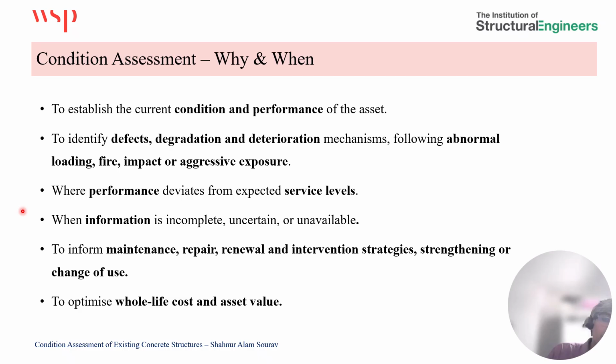So why and when do we do condition assessment? We do condition assessment to establish the current condition and performance of the asset. If we identify any defects or degradation or deterioration process that is happening within the concrete, we want to know the severity and extent of these defects. We also do it when the performance does not meet the expected service level, or where there is limited information or no information, for example, we don't have any design information or design drawings or as-built drawings.